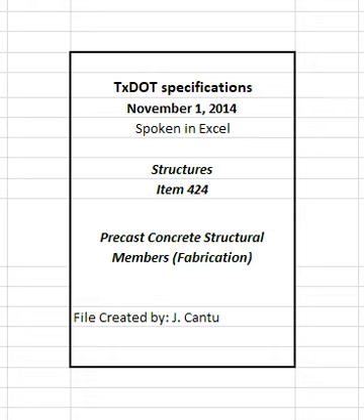Mix concrete for a period of 1 minute for 1 cubic yard and 15 seconds for each additional cubic yard of rated capacity of the mixer. Count the mixing time from the time all materials are in the drum. Increase mixing time if necessary to achieve a uniform mix.